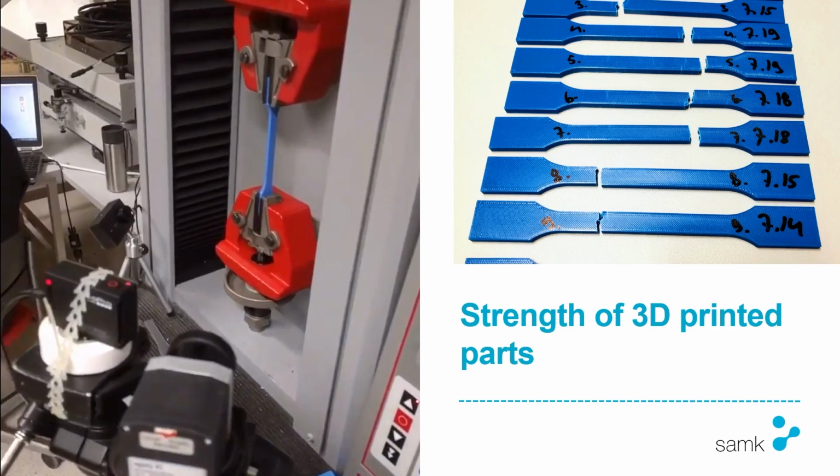But if we printed them in the position shown on the left image, the upward position, we could see that the weakest link wasn't the material itself, but its internal bonding. So the plastic didn't bond so well, and it snapped quite easily.